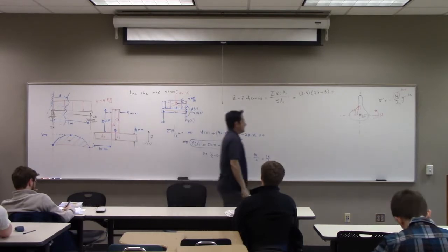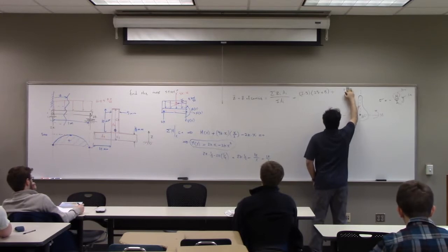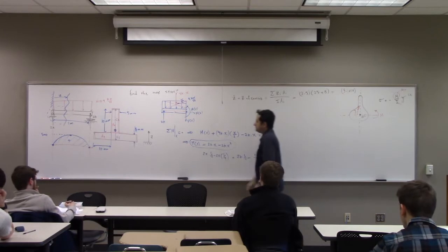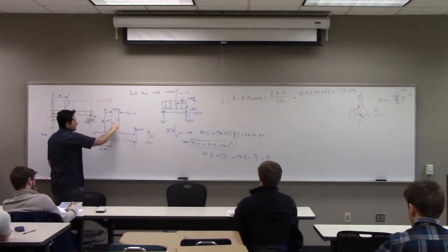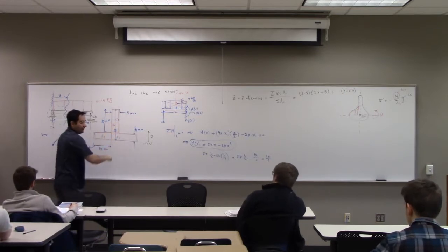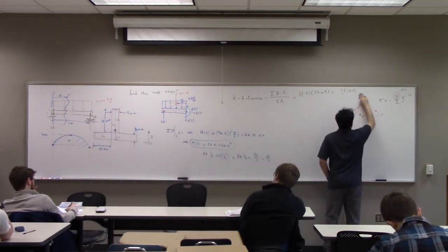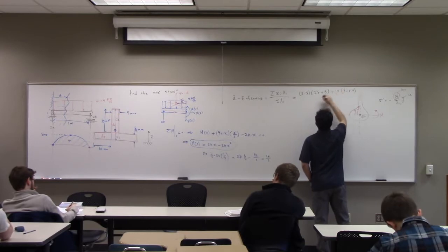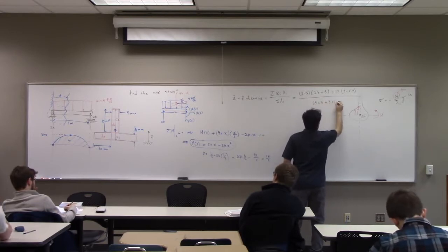A2 is equal to 5 times 10, and the centroid is equal to 5, half of this from here to here, plus an extra 5, which is equal to 10. So that's times 10, divided by 25 times 5 plus 5 times 10.